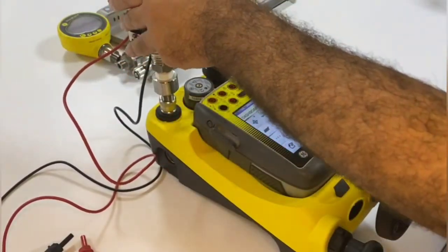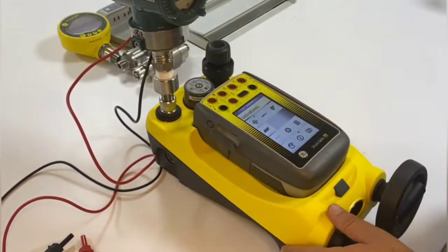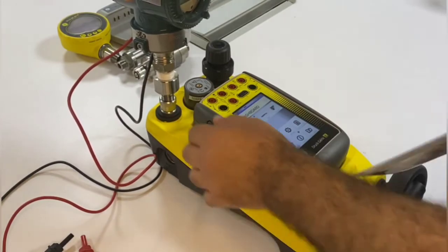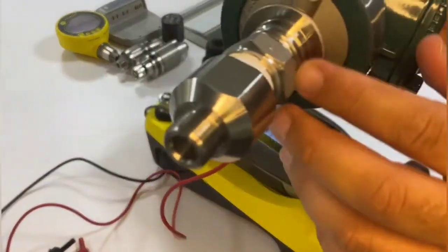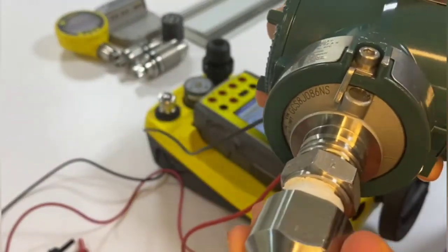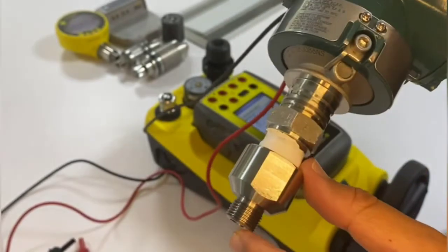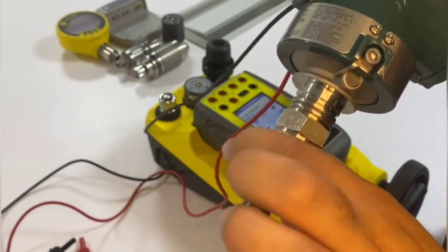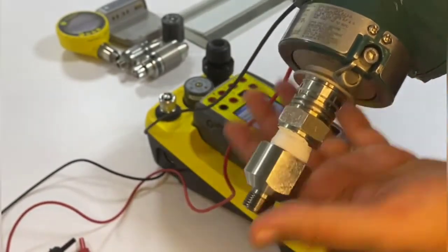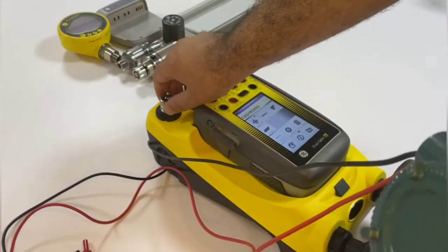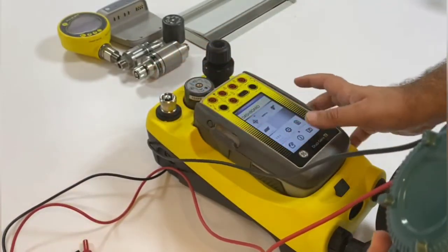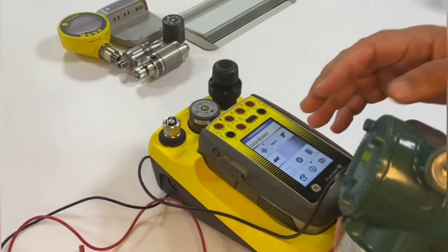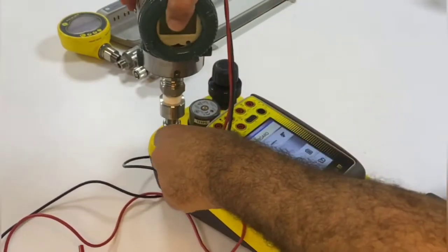So the devices of Druck are all ready for quick fit. So this is the transmitter, half-inch. I already put the half-inch quick fit using my tools on my Teflon without putting any tools in the calibrator side. Now, if I move to the calibrator side, I'll tighten by hand only.